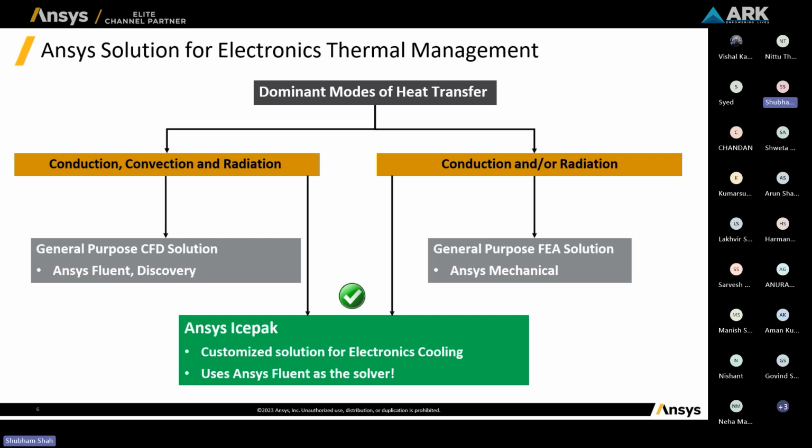How will we get this kind of heat transfer in our simulation tool? Is it available or not? Conduction, convection, and radiation are general purpose and included in Ansys Fluent as well as Discovery as well as in Icepak.